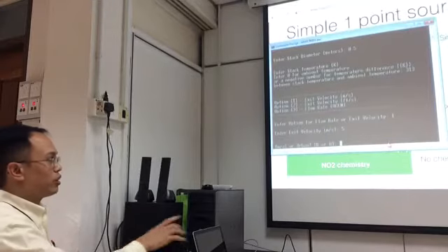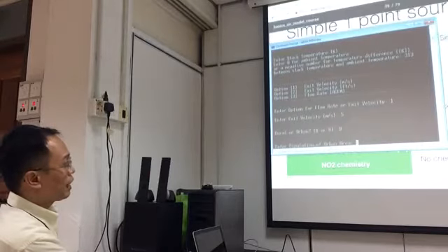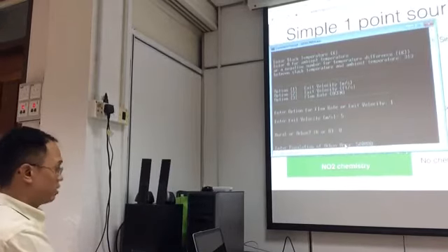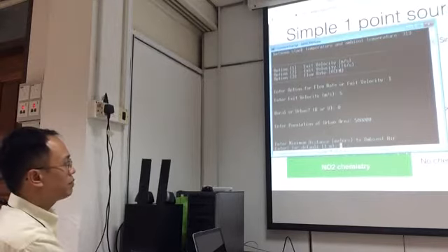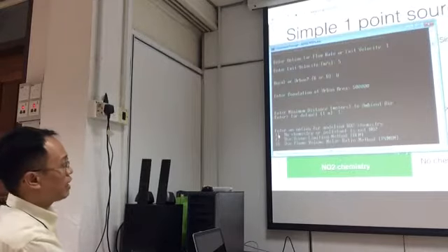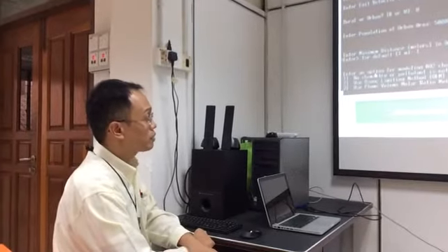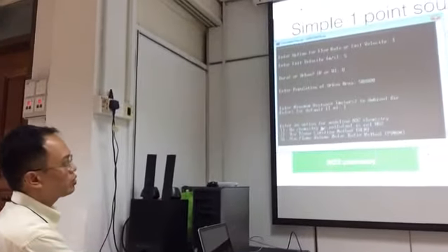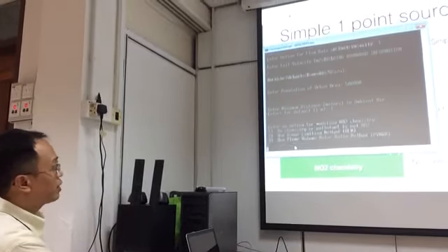Okay, is the surrounding area rural or urban? So I just choose urban. And then what is the population of the urban area? Just an estimate, about 500,000. What is the minimum distance to ambient air? So the default is 1, so we just use the default. And then whether we want to consider any atmospheric chemistry inside this model for the run, we just go for the simplest one. There's no chemistry, so we use option number 1. No chemistry or pollutant is not nitrogen dioxide. Just choose option 1, press enter.